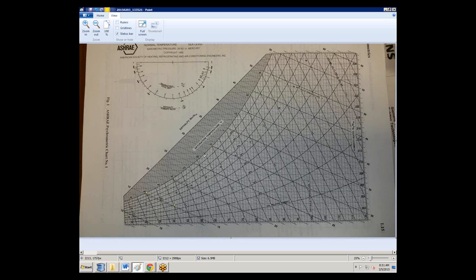So it's a lot easier to say, oh, my return wet bulb is 60 and my outside wet bulb is 58, so I'm going to bring in outside air right now, even though the chiller is running. Those are the two main areas where we want to make sure that our wet bulb calculations are accurate. And that gets us all the way up into, if it's 75-degree return air and whatever percent humidity, say 60%, obviously we want to make sure that that's being calculated properly.